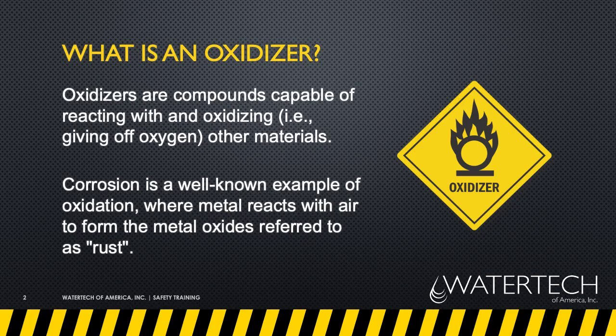To give you an example, WaterTech had an instance where a few drops of ferric chloride got into a drum of hydrogen peroxide. This caused a reaction which released oxygen from the drum of peroxide. The amount of oxygen generated could not escape quickly enough through the drum openings. The resulting release of oxygen was violent enough to cause the chemical feed pump on top of the tank to shoot up towards the ceiling. It smashed into the fluorescent light and shattered it. The drum itself split in half due to the vapor pressure. That's how much pressure built up in the peroxide drum from a couple of drops of ferric chloride.